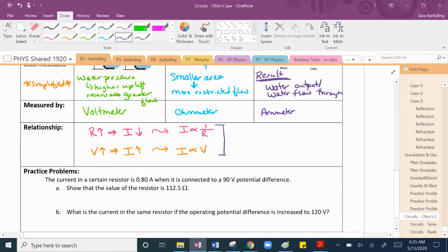And the thing that's really important here, when you're going through this idea, is that current is the result of having a voltage, right? Or energy given to charges and them moving through something that's got resistance. So those two pieces have to be there. Okay, so we can put these things together and we can say that the current is dependent on both the voltage and the resistance. One of them is a direct proportion, the other's inverse. And this right here is the rule that governs most of basic circuits. Okay, and this rule here is Ohm's law.